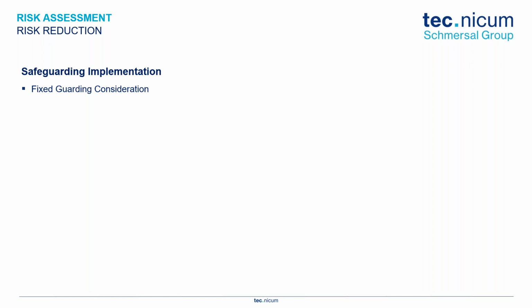That's part of the risk assessment, fixing the issue. So there are some things we have to consider with fixed guarding. In the example that we saw with the cylinder, we added some hard guards to prevent access. And I always say, when you start trying to do a risk assessment, let's lead with fixed guarding, and I'll explain why at the end of this slide.